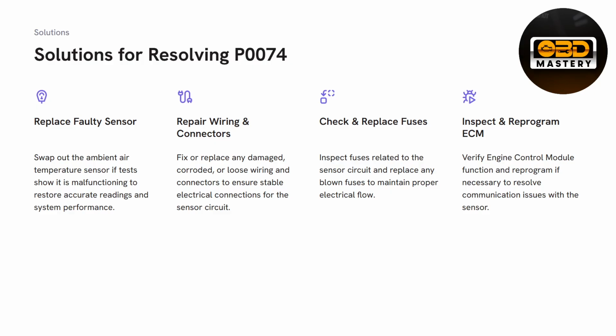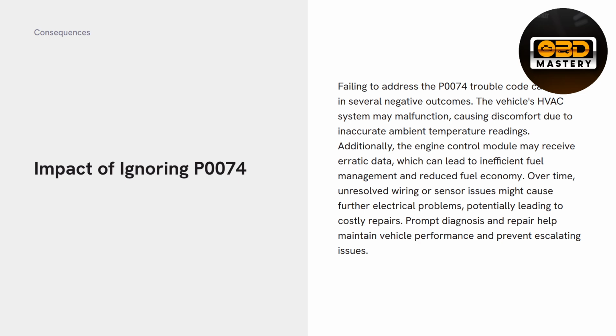Consequences. Failing to address the P0074 trouble code can result in several negative outcomes. The vehicle's HVAC system may malfunction, causing discomfort due to inaccurate ambient temperature readings.